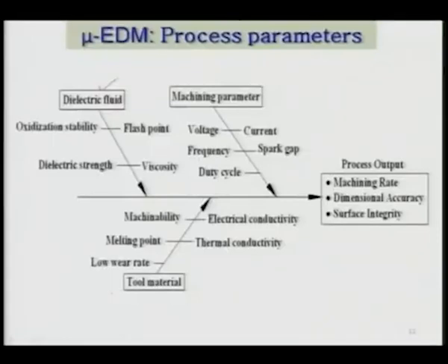Then there is the tool material. Tool material should have easy machinability, so that you can give a complicated or any desired shape to the tool, because what you are going to get on the workpiece is the replica of the tool, very close to the replica.